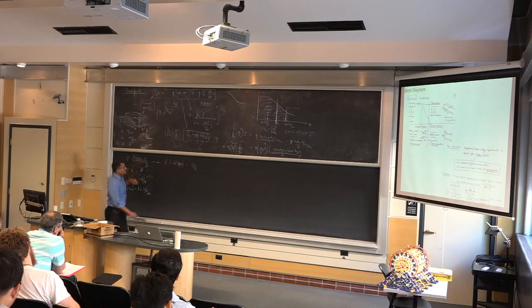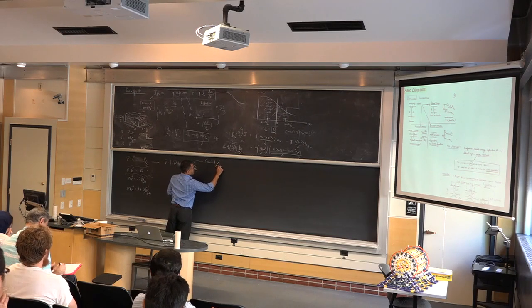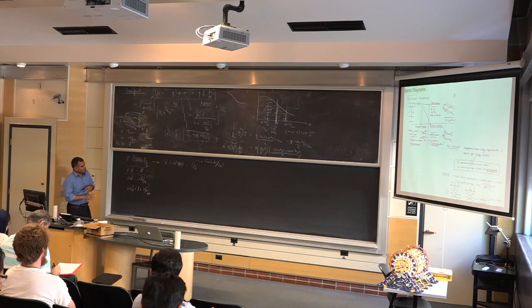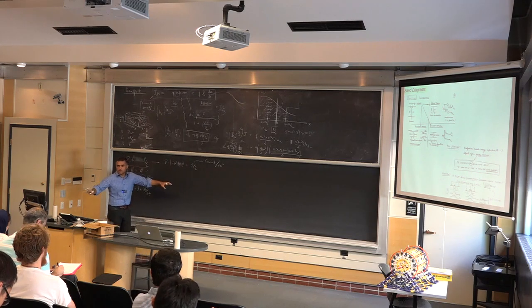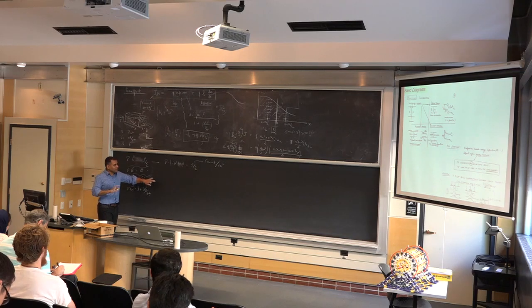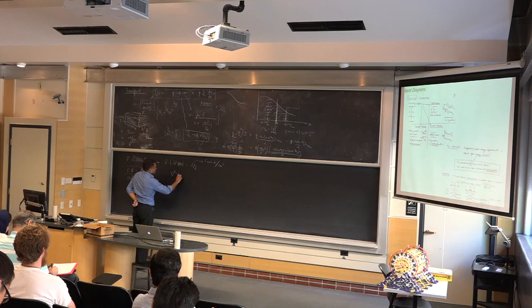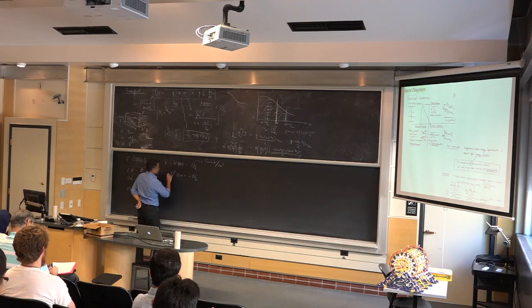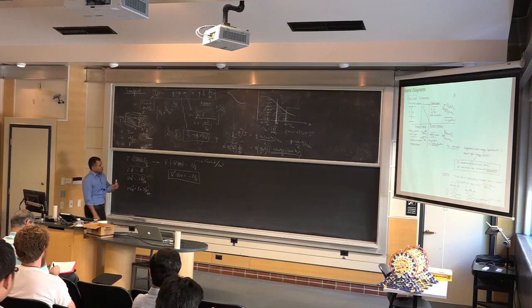Charge density, rho, is the charge density in coulombs over volume. It's the net charge; it doesn't care about whether you're talking electrons or holes or donors, etc. It only wants the total charge. Give me the final number. After all the positives and negatives have cancelled, what's left is what charge there is. And this is the Poisson equation. That's what we are really solving most of the time for energy band diagrams.